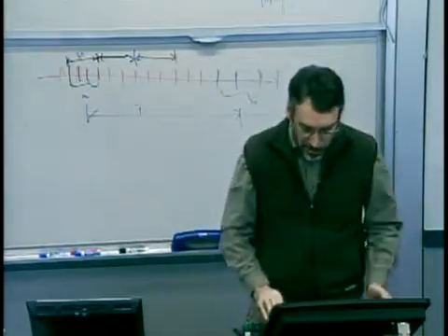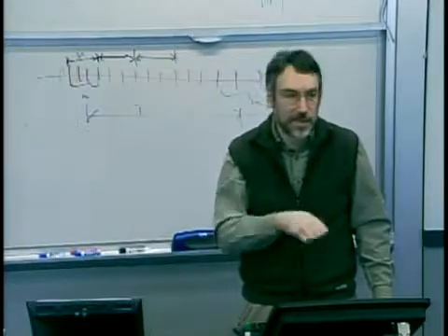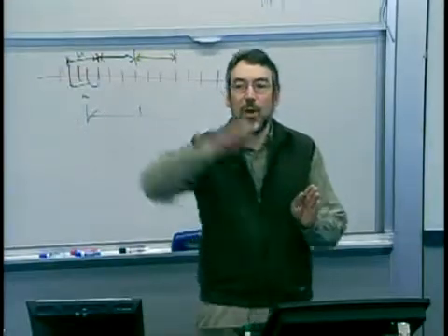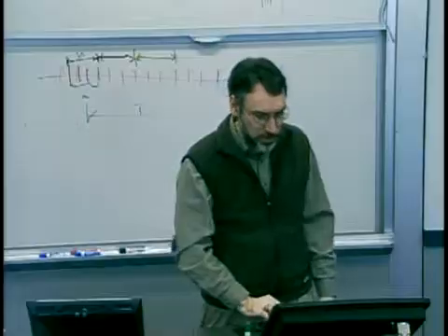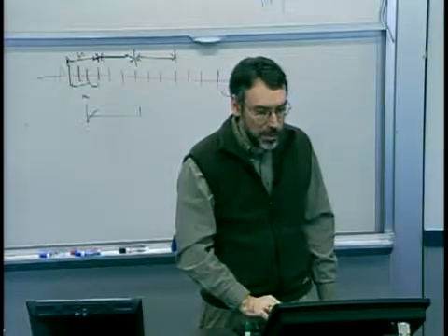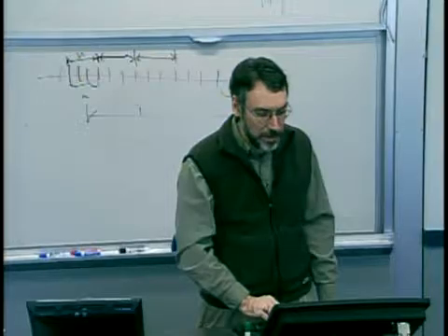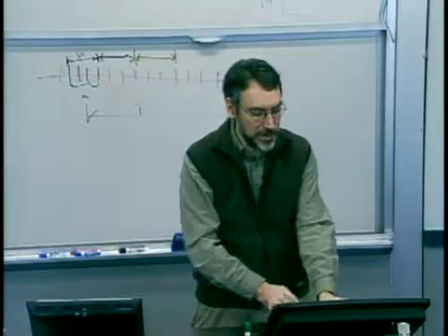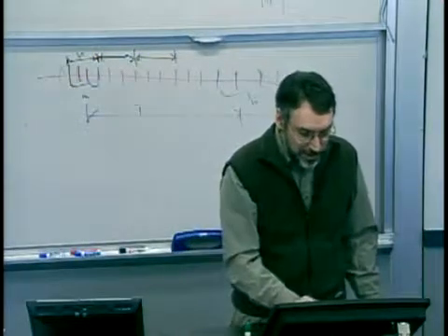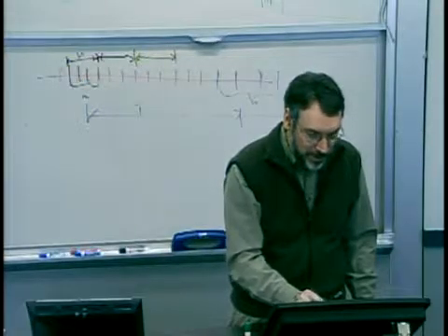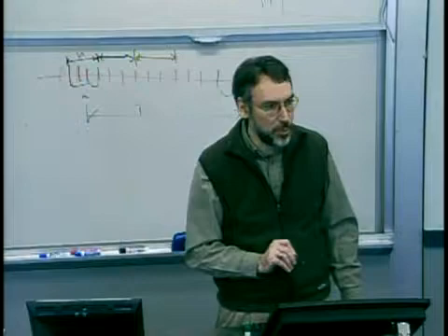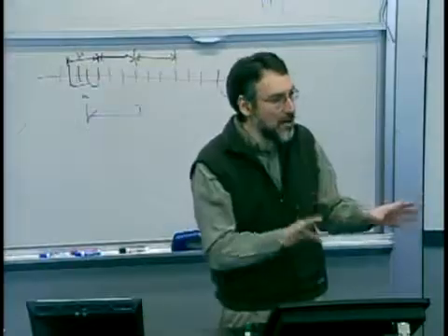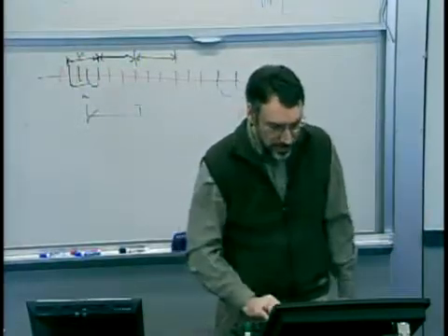And the point is simply here that if you're sampling from some physical processes, there may be an inherent correlation that isn't the one you're trying to get at. You're trying to detect long-term trends and not detect very small shifts. And so you can play around with the sample time compared to the inherent correlation of the process. And all this is saying is you want to pick your sample time ultimately such that if I pick this sample here and then my sample time some point later, this underlying short-term correlation is not what I'm detecting. I'm detecting again a big mean shift.